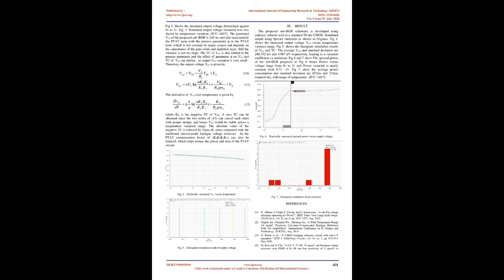Reference voltage with nominally zero temperature coefficient is obtained with negative and positive TC voltage. The circuit is designed using 90nm CMOS technology. The operational amplifier OPA shown in Fig 2 enforces that the nodes have equal potential. The OPA uses the folded cascode structure to improve the loop gain and power. The offset voltage of the OPA can be minimized by using large size input transistors and coupling capacitor.